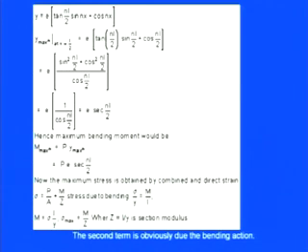We have the value 1 by cos of nL/2, or we can say e times sec of nL/2. So the maximum bending moment in this case would be exactly equal to the maximum moment due to the axial load P times y maximum.